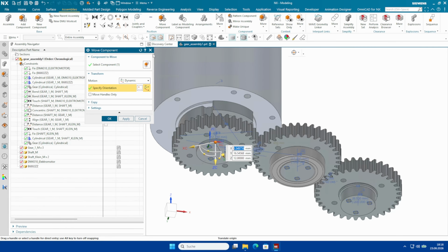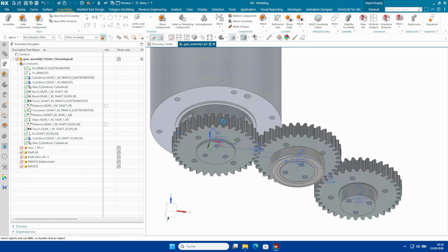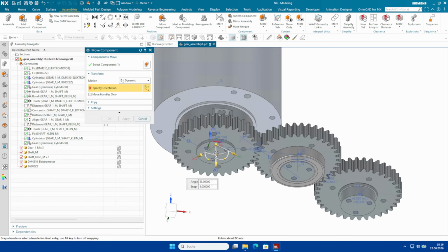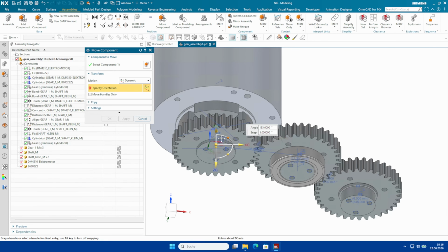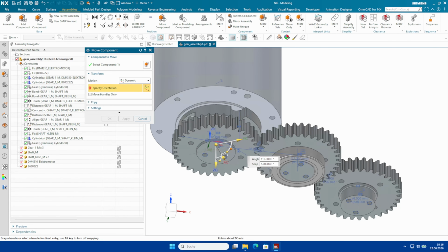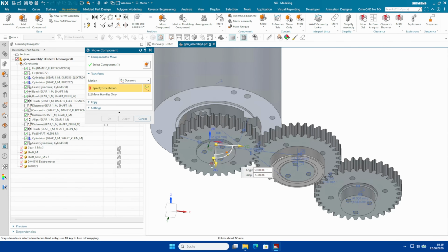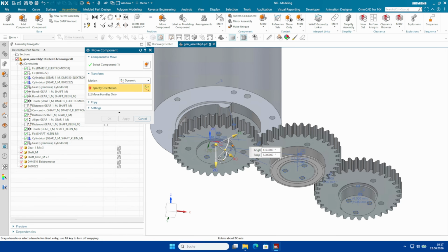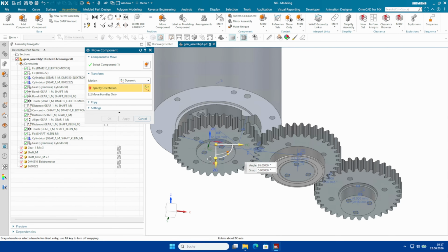Again, this is moving in the opposite direction, so I have to fix that as well for the reverse direction, and that should fix it fully. Yep, that fixes the gear assembly, and now everything works properly. The shaft on the third gear is obviously fixed, but for it to not be fixed, you have to go again, add a different component, set it fixed, and then constrain it with the gear with a cylindrical constraint, and then try to add a gear to the other gear so that it rotates. But this is how a gear assembly works,